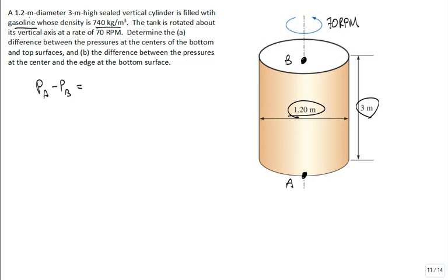All right, so let me back up a little bit. We have just developed the governing differential equations for how the pressure changes in the r direction and in the z direction. Then we actually solved for the equation like this. P is equal to some pressure at the center at some reference elevation, plus rho omega squared r squared. Did I have that 2 in there?